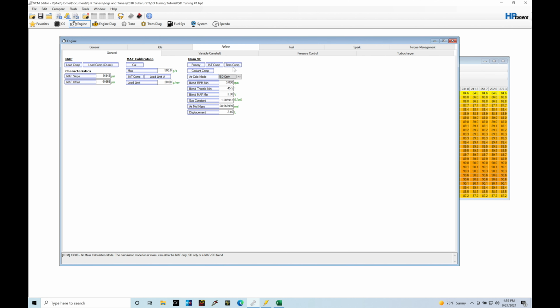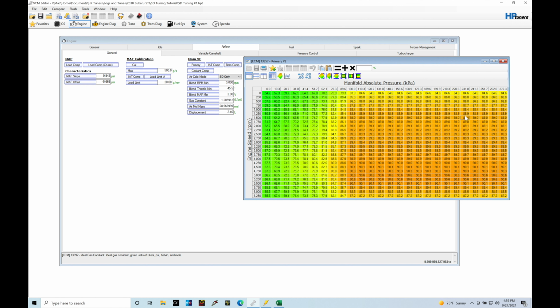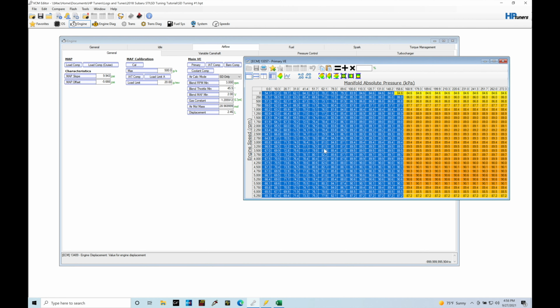Now, in this case, with SD only, the table here is going to be an estimation of air mass coming into our engine. Where the mass airflow sensor was directly measuring the air mass, we're going to be estimating it. So we actually have to build this table out so the values in the table are going to be valid and they're going to work. Now, I'm going to outline how to do that here in this tutorial, specifically taking a look at our 0 to roughly 140, 150 kPa range. We can use our front...